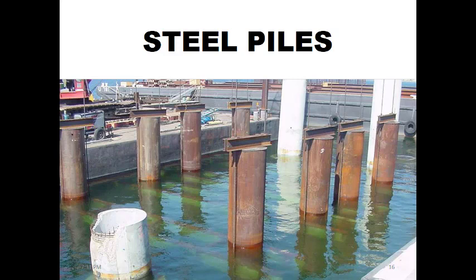When you need to nail it, you have to be careful not to hit it so hard that you will break the core side of a pile, like you can see in this picture. While there are some remedies for that, like putting metallic gaskets on top of it and then loading it as initially intended, the broken pile is not something desired, because the breakage can happen not only on the tip that is visible and easy to put a gasket on, but it can also happen while the pile is in the soil,